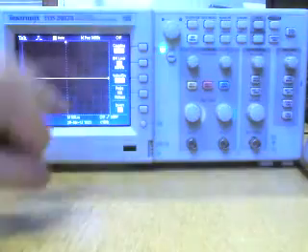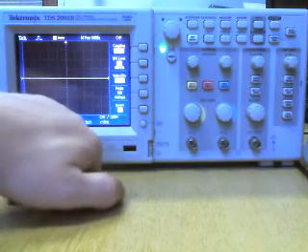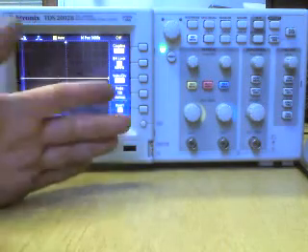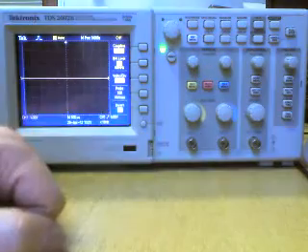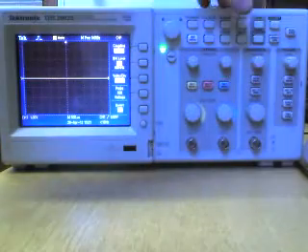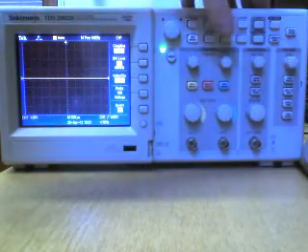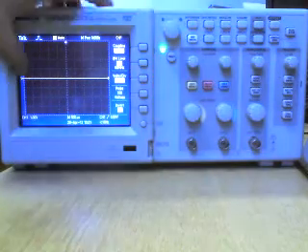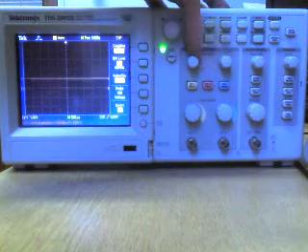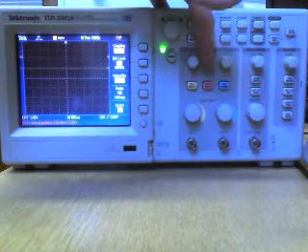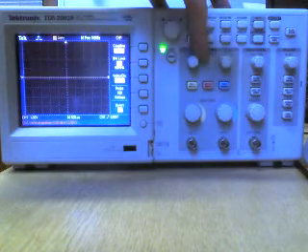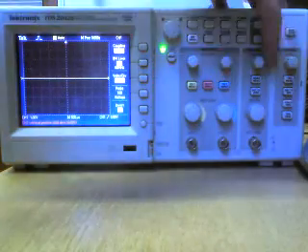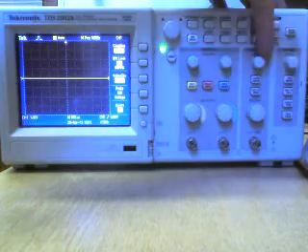Our time base is now more or less in the centre of the screen. It's currently set to 500 microseconds per division. You might want to change that, you might not want to change that. It's perfectly fine. Okay, the only thing that we need to worry about is our vertical position. Default setup sets it to the centre of the screen, but you may want to move it to the bottom, you may want to move it up if you're displaying two waveforms, or you may want to keep life simple, just keep it in the middle. Horizontal position is where our waveform starts.